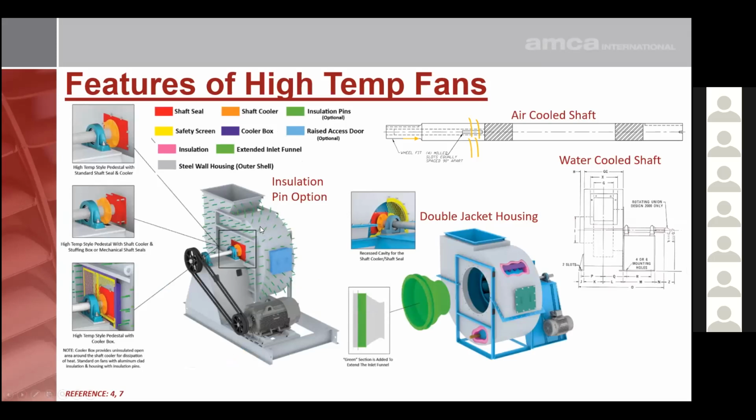So, features of high temperature fans. The first thing is these will have a cooling wheel to cool the bearings, as you can see here. You will have some studs on the housing so that you can put an insulation jacket on top of the fan. You will see a raised access door to accommodate that insulation jacket. On the right, you'll see a double jacketed design. This is a lot more expensive, but also a lot more efficient.